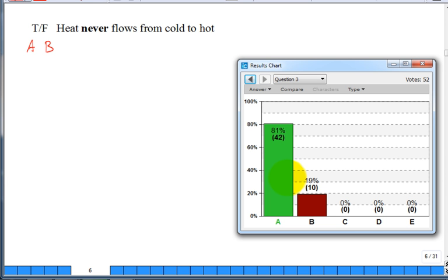Professor, how do we get refrigeration systems? Well, what you're doing is pounding on that refrigerant, beating it up to boost its temperature so you can dump heat to something that's less cold than the refrigerant, like the outside on a hot day. But you put it through a compressor to achieve that. And then when you put it through the expansion valve, it drops the pressure. All of a sudden it's cold. The fluid in the evaporator is really cold compared to the air blowing over it. Again, heat flows from warmer to colder. It's a clever engineer that pumps water uphill and moves heat from something cold to hot. But it doesn't come naturally.